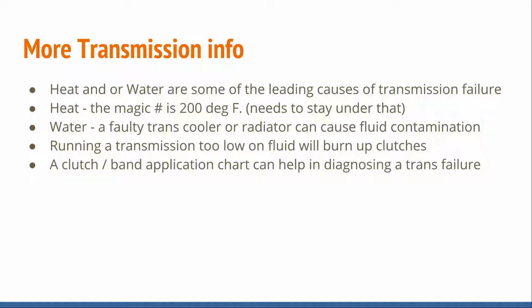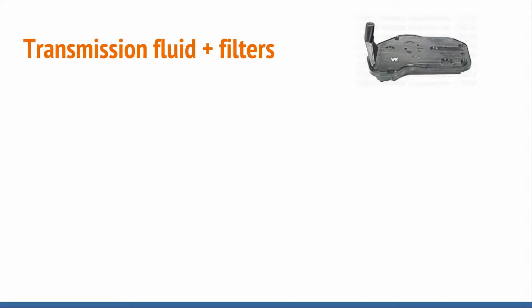On the other hand, you go drive a vehicle and it only has third gear. You throw the scanner on it, you go to gear command, guess what? The computer is telling it to be in third gear. So the transmission's doing exactly what it's being told. It's not being told to shift gears. It's being told to stay in third gear. So sometimes transmissions are stuck in third gear. If a certain code's being set, we call that limp mode. It goes into like a limp home mode. But anyway, okay, moving on. I could talk all day about that.